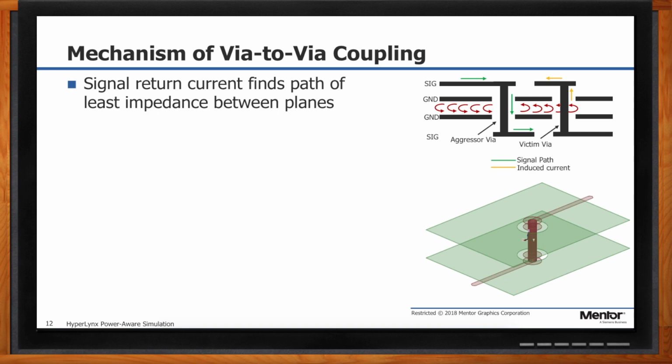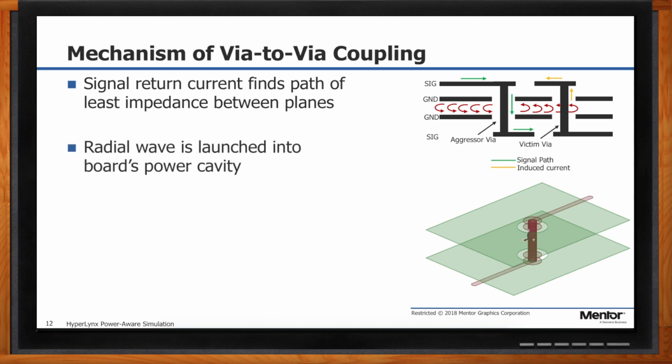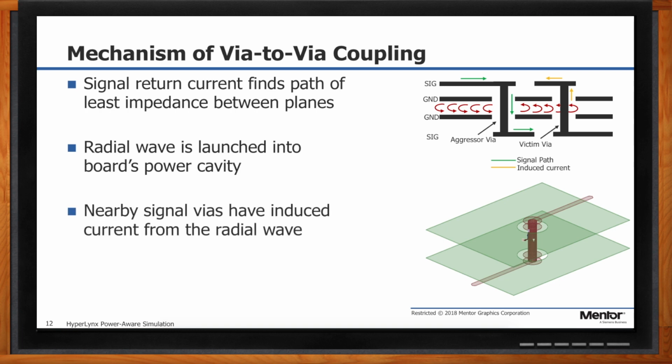And then what happens is that that current goes through the board and goes to some other trace on a lower level of the board, for example, and there's a different reference plane that that return current is flowing on. And as that energy goes through the board, as that current goes through the board, it's actually going to create a magnetic field that's going to go sideways out through those planes. Think of it as sort of blowing energy into the cavity. Probably a poor visual image, but let's just stick with it for now.